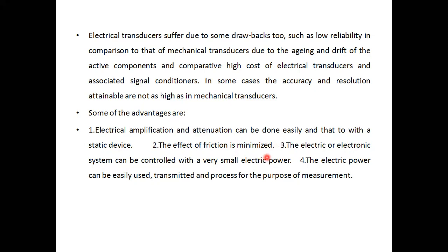In industries, I can operate any electronic or electrical device with the help of 24 volts DC. Just 24 volts DC is the industrial standard to automate a process, right? So for the automation of a process, I will use 24 volts DC, and wherever necessary, I go for 230 volts if I am working on solenoid valves, likewise, right?